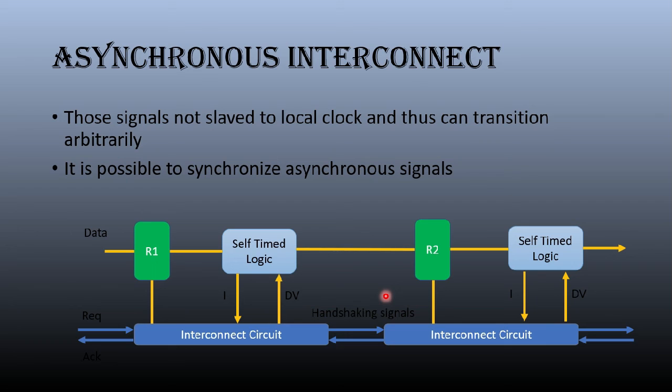When we interface an asynchronous system, for example your flash drive, if you insert it into the laptop, the data transfer happens between that asynchronous circuit and the synchronous circuit through a protocol. There are different types of protocols for that. So in summary, asynchronous systems are much faster and much more efficient with respect to computation and speed, but they have complexity with respect to the area and the amount of logic needed.